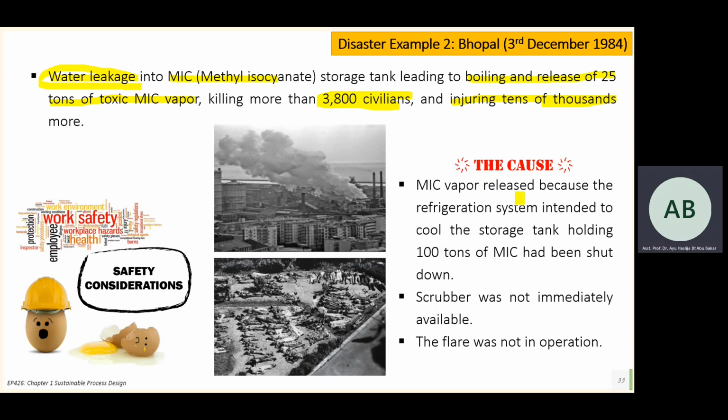The cause, MIC vapor release because the refrigeration system had been shut down. Okay, refrigerator system had been shut down. So scrubber was not immediately available. Flare was not in operation.